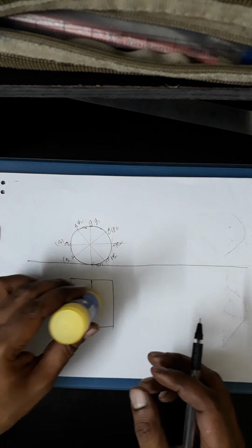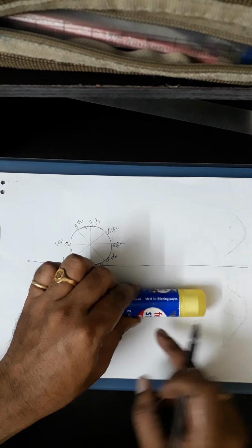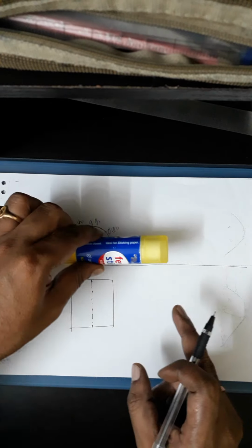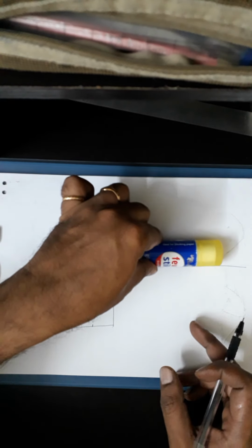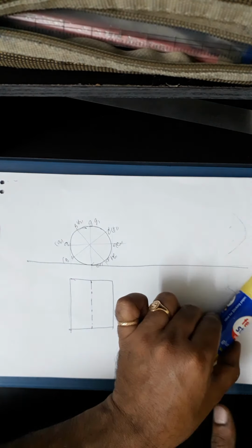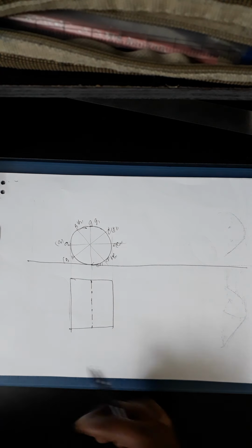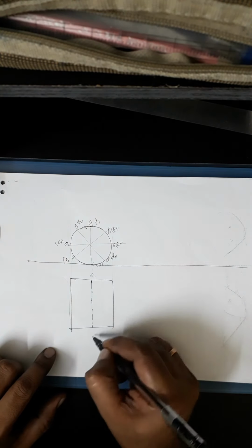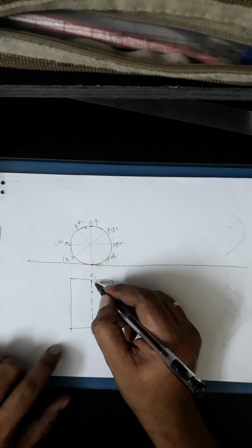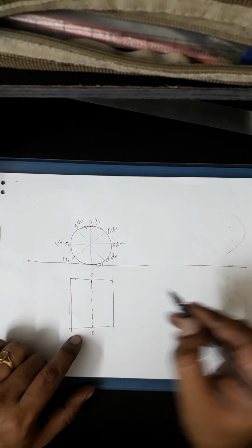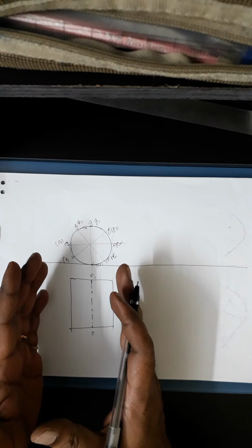If otherwise you have to go for drawing this, completely resting on one of its generators, then you're going to get it in this way. First view, then redraw this, get one more. Then you have to go for the 3 steps method. Otherwise, similar to the prisms, you can draw directly in 3 steps. Okay, so this is O1O. So redraw that, because this will be now parallel to HP and it will be the true length. The axis will be given inclined to only VP.